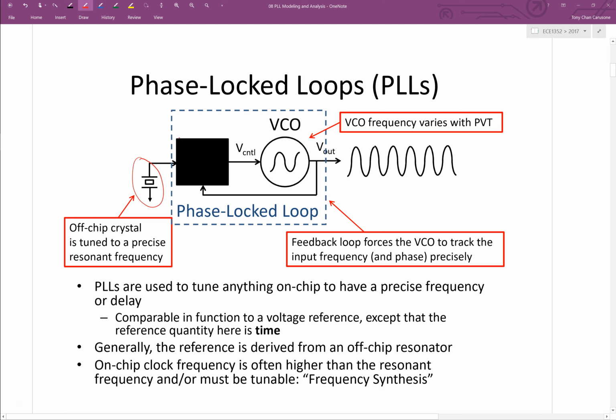So the active circuitry needed to do that would have to be on the chip. The crystal on its own is typically a passive component. Sometimes the circuits that are needed to make the crystal oscillate are integrated right alongside the crystal on a separate package. But that may or may not be the case. The least expensive component you can buy is just a pure passive crystal that then requires some active circuitry to get it to oscillate.